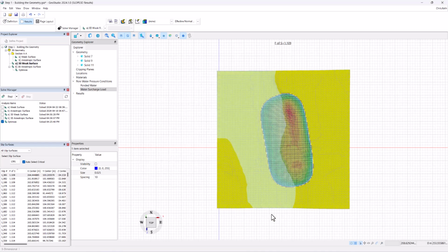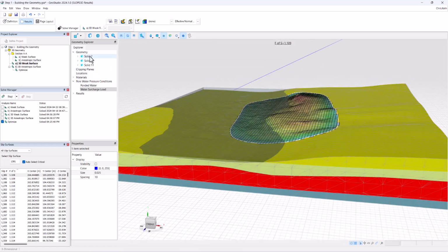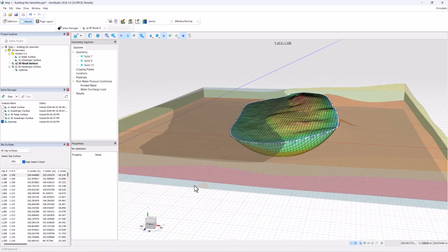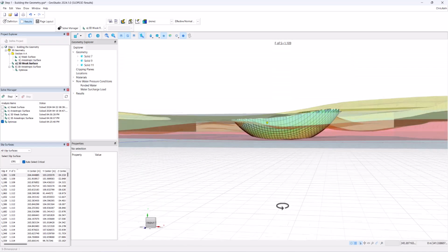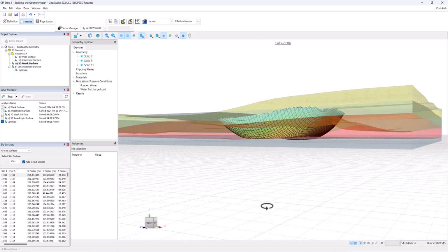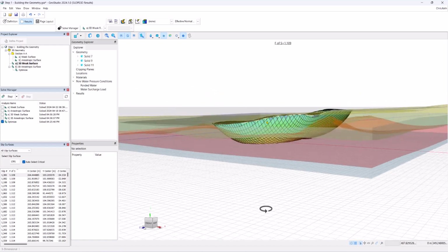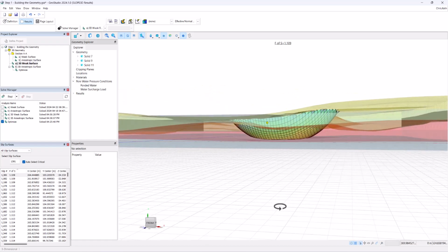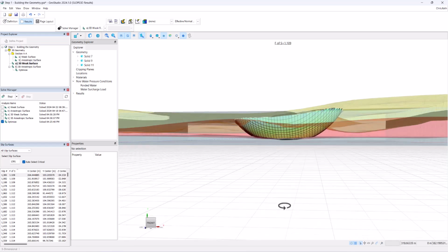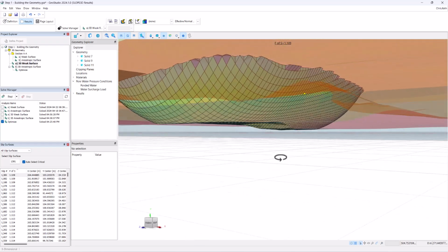Okay, with that done, I'm now going to rotate into a side view and zoom in and change the transparency of these three geological model volumes to 0.2, just to demonstrate that in the same manner that the weak surface caused translational mode of failure in 2D, we see the exact same behavior in 3D, in that our background mesh, which serves as our weak surface, acts to truncate the ellipsoid, creating this fairly flat bottom in shape.